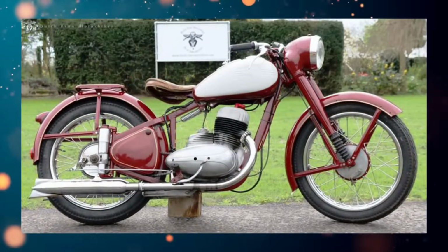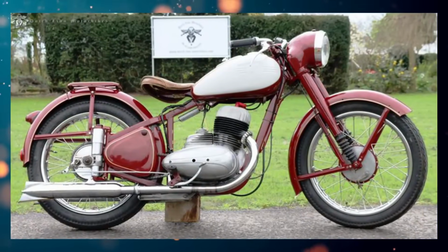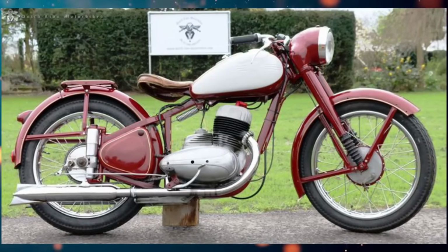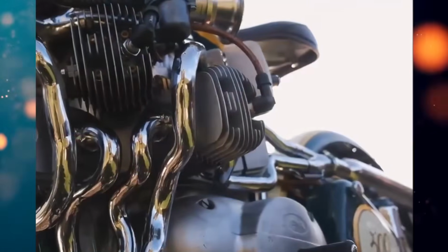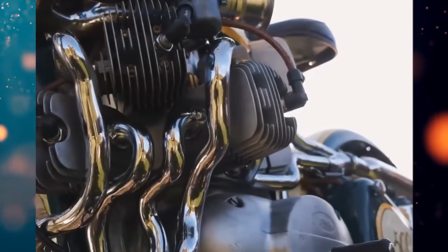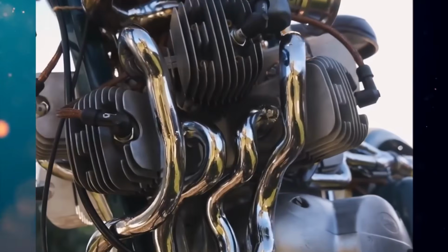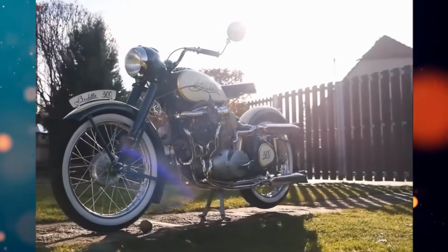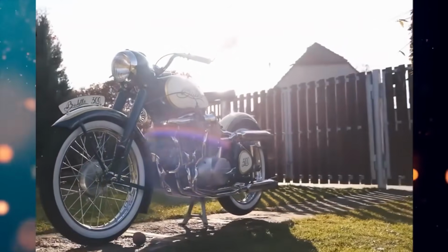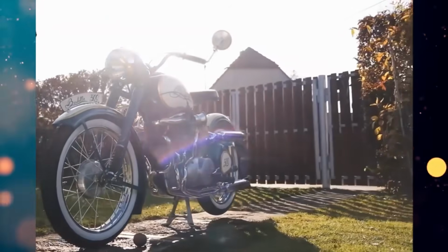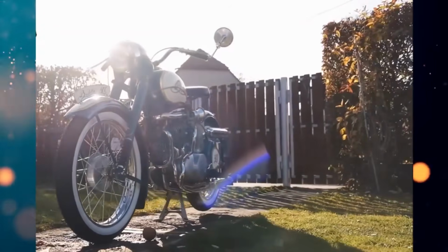The Jawa Perak motorcycle served as the base, with engine dimensions adjusted to fit the Jawa frame. The cylinders for the engine were taken from 50 cubic Jawa motorcycles, and to increase the power, 5 Roots superchargers were used. At the time of its debut in 2021, the power was limited to 60 horsepower at 6,500 revolutions per minute.